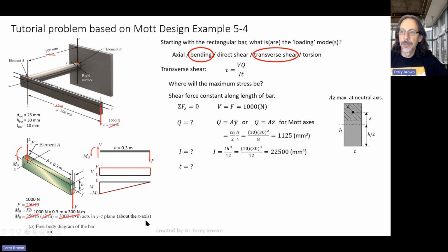And the T here is the width, turn around, right? The width that we're looking at here of our beam. So we're pushing down on our beam to get the shear along this way. The other dimension that gives us the stress, shear stress, is that width or thickness of the beam. Okay, so in this case it's 10. Now here T and T on the diagram are the same things, but they may not be, right? Same as we had before, right?